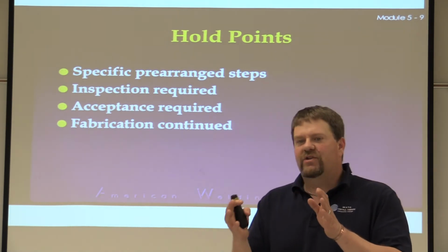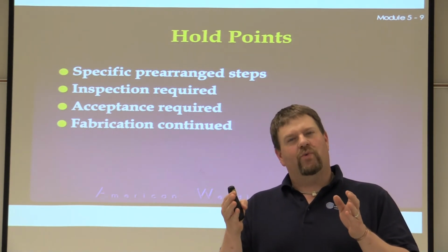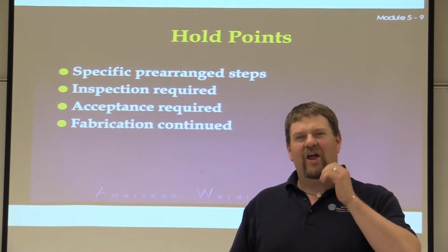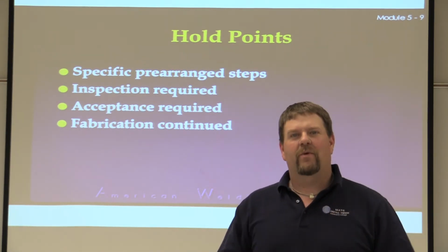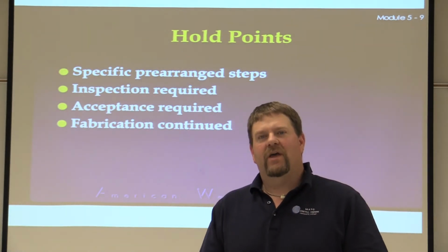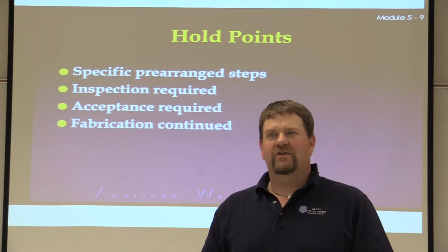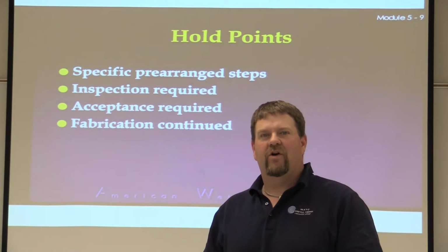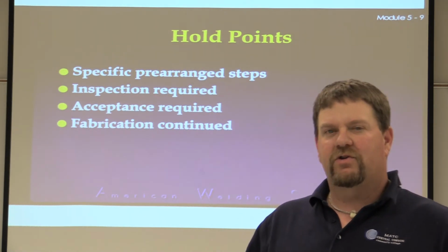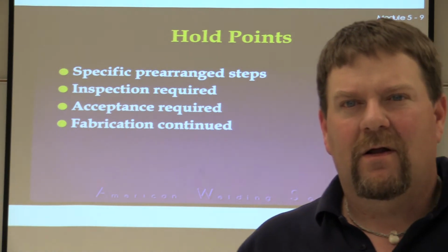And what we're trying to do is avoid something I've seen a lot: bolts welded inside of projects because they weren't cut to the right length, and somebody just went in there and started whipping a whole bunch of electrode in there, filled that gap, and yeah, they filled it up. But guess what? On the inside of that root, it looked horrible, right? And there's a bolt in there, and somebody just kind of welded over top of it because somebody wasn't very good at the oxy-fuel cutting, or they didn't do a good job of fitting this piece up, okay? And that's important in here as well.